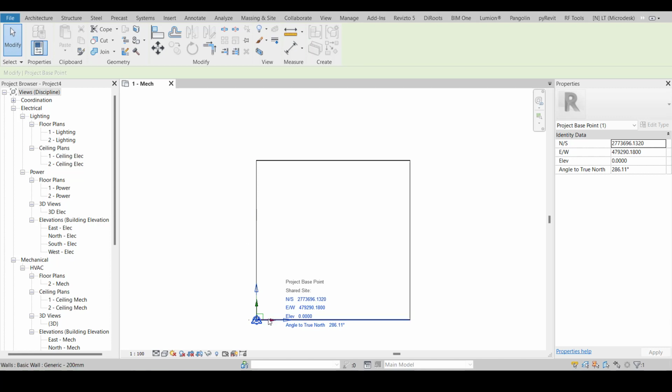Only thing is, if the coordinate of this project base point is an actual point of earth, then whatever marking we do here to find out the coordinates, we can get that point by using machines also. For example, total station or GPS system if you have, and if you give the coordinate point, automatically you can go and find that place. But if you are doing it manually like this, this is 0 0, then your GPS will not tell that location.